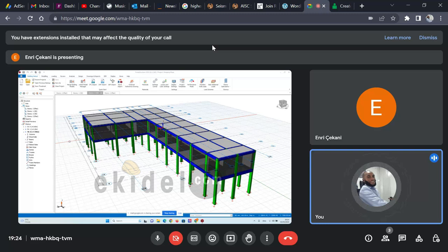Now, a reinforced concrete section: how to make a reinforced concrete section ductile. The first thing that you have to do is just two things. One, either you reduce the load of the compression zone, or two, you increase the strength and ultimate deformation of the compression zone. I will first go to the first one, which is to reduce the load of the compression zone. When we talk about reducing the load of the compression zone, we talk about limiting the axial force in the section, or using compression reinforcement, or limiting the ratio of the tension reinforcement.